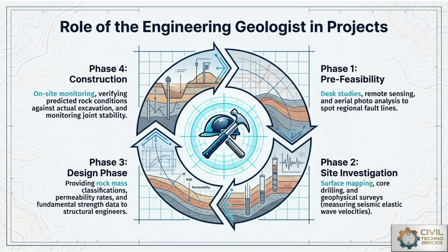And the last phase is related to the construction activity, which is the on-site monitoring, which verifies and predicts the rock conditions based on some geological characteristics against the actual excavation and monitoring joint stability. Here, the role of the engineering geologist is most important, to study the existing rock beneath the proposed construction activity, and the whole geological subsurface investigation criteria is designed according to the project, like a dam, tunnel, etc. So continuous geological assessment minimizes the risk and failures in the future.